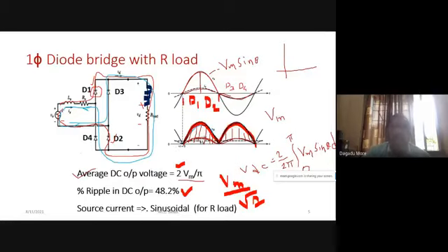Here our DC current has the same wave shape as the supply voltage. But when you put a very large value of inductance, then our DC current, IDC, will be smooth and ripple free. Are you getting it? This is the ID I am showing here.